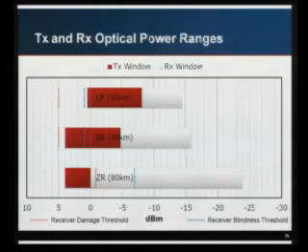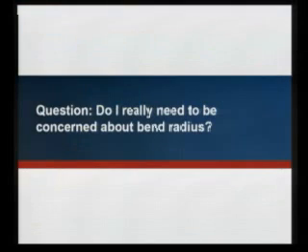And then, like I said, when you get into the long reach optics, you see the huge difference in receive sensitivity. Because this receiver is now more sensitive, it's more susceptible to damage. And so the damage threshold is now moved down not into what it might transmit, but even below what it might transmit. So if you're doing things below 20 kilometers, you still need to pad these 80 kilometer optics to prevent damage. But it's really a function of the receiver, not the transmitter. So people keep that in mind.